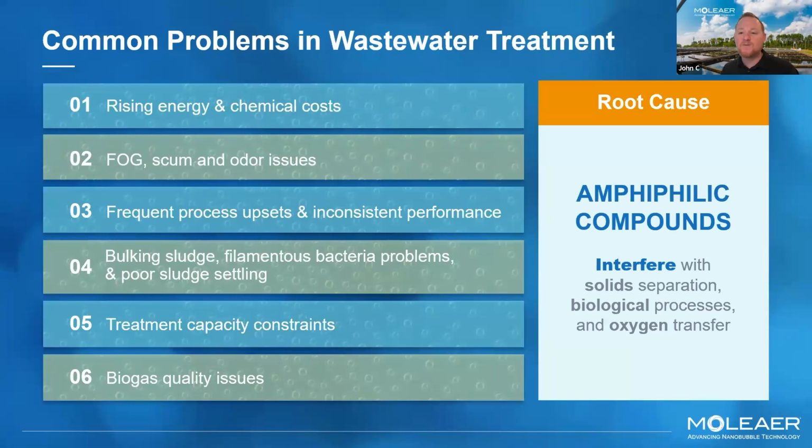But what we're seeing at wastewater treatment plants, and at the plant that I used to work at, is that we're at our solids loading capacity for the wastewater treatment plant at nearly half the hydraulic flow. Lastly, as we go to attaining net neutrality on our energy usage, biogas quality is the most important. We need to be able to generate as much electricity on site.